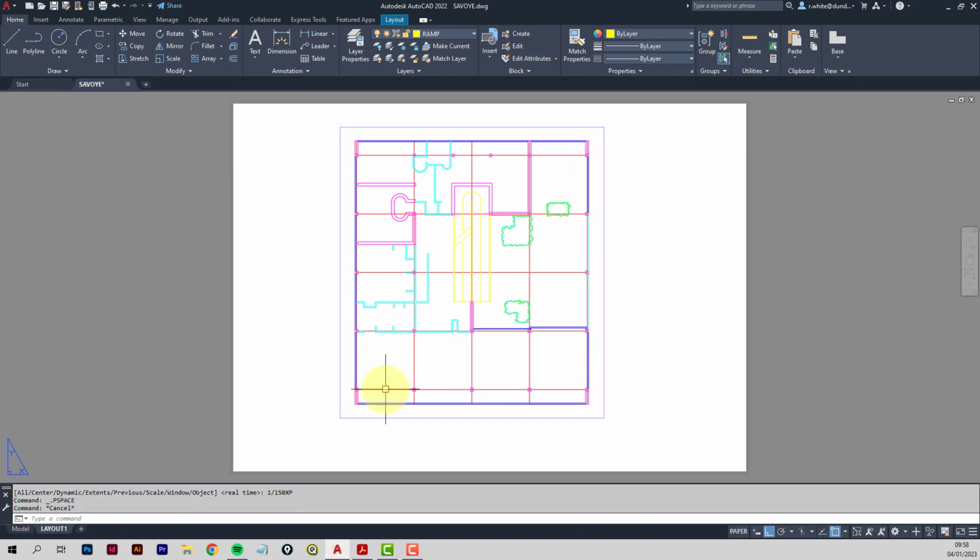Now, do you notice the grid lines aren't showing broken now? So what looks okay in model space tends to not look correct for paper space. So what we need to do is a command called LTS, and it's short for line type scale. So it's LTS, enter, and 1, enter. If we want to see more breaks in the lines, more dashes, then we do like 0.75 or 0.5. So LTS 0.75, and see the lines look more broken. That looks fine like that.